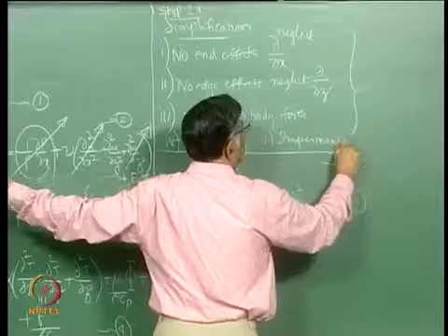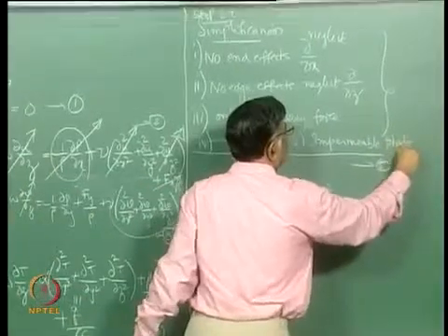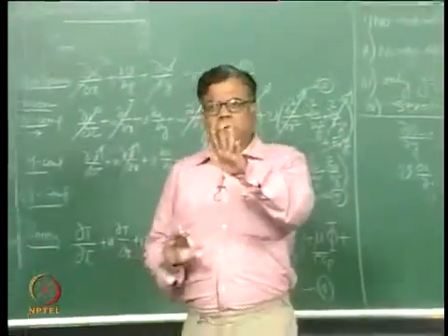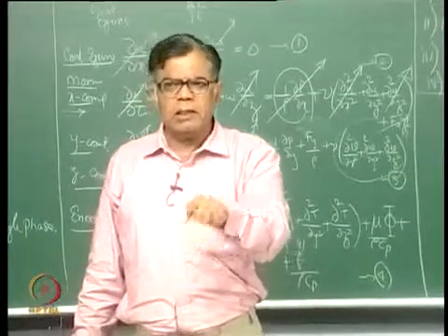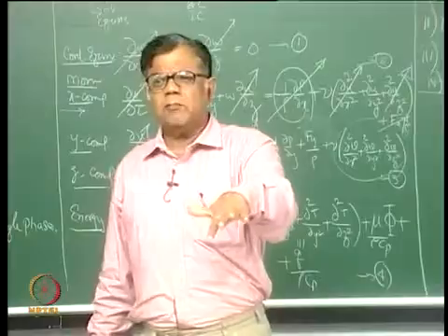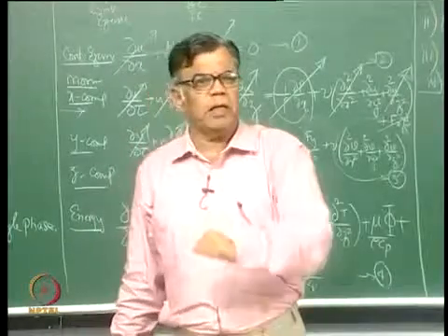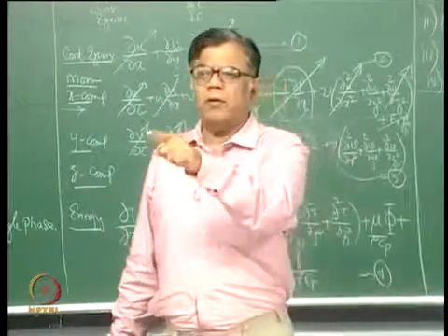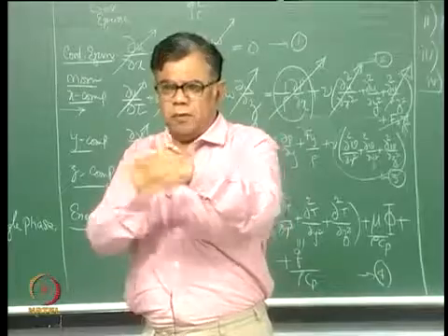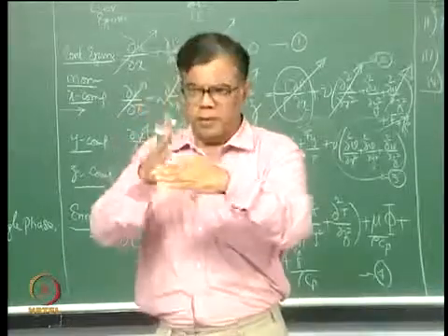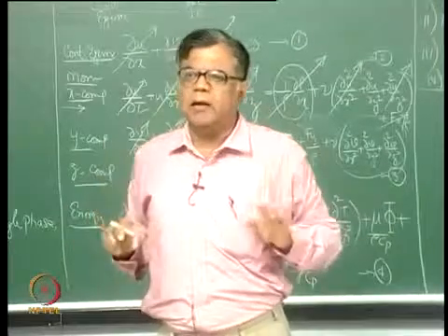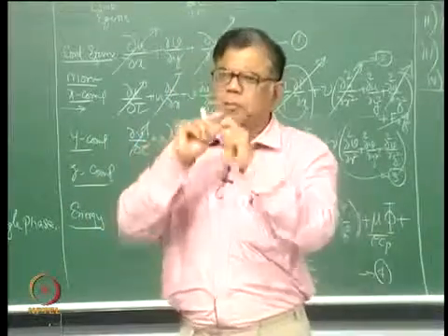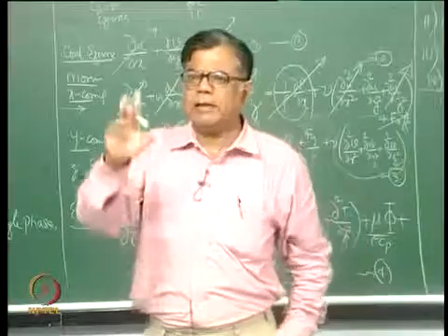Actually I could have written it right there. Now, just because there is an impermeable plate, do you think there is no V? There is another condition where for an impermeable plate there could be V. If there are holes and you put in air or whatever fluid, that is suction or blowing. But I would like to state that V could be there even for my impermeable plate under certain conditions.